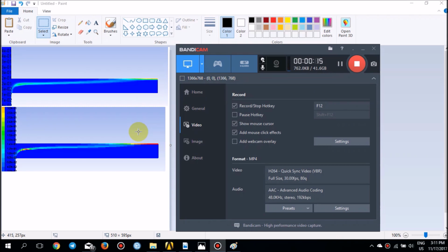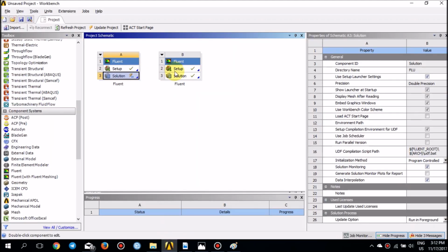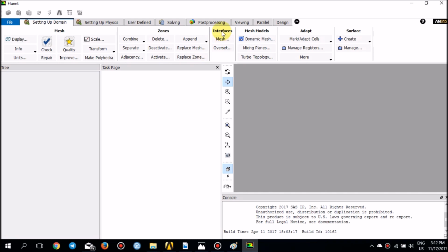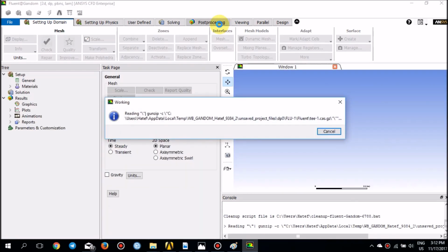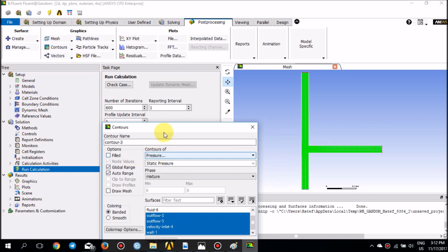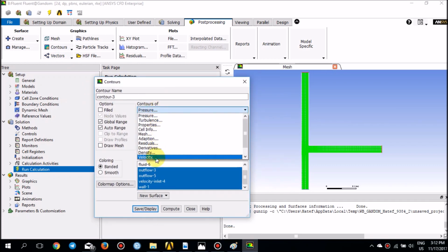So if you compare the volume fraction of air for the mixture model, you see that this air pocket on the top is much bigger and much more elongated, but for the Eulerian, the air is much more transported with the water before it accumulates on the top. And the reason is basically, if I take a look at the pressure or the velocity contour plots in the Eulerian, let me explain on the contour plots of, let's say, velocity.